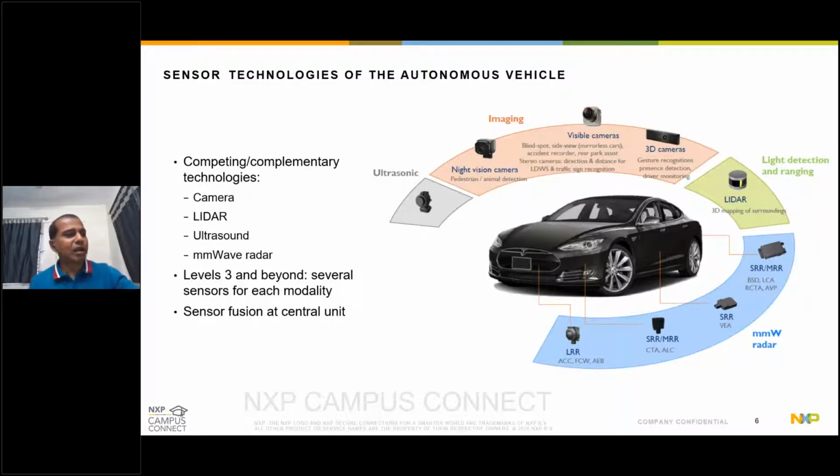Here I mentioned another word called sensor fusion. So what does sensor fusion mean? A system will have multiple sensors, not a single sensor. Sensor fusion is the ability to bring together inputs from multiple radars, lidars, and cameras to form a single model or image of the environment around the vehicle. The resulting model is more accurate because it balances the strengths of the different sensors.